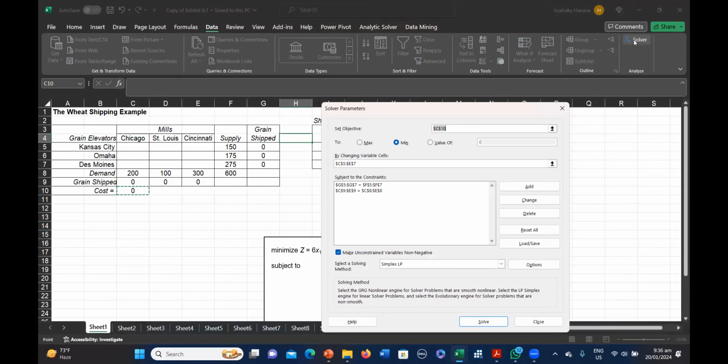So when you click on your solver, you will see this window showing up where the solution has been set up, but you can reset it for us to go through again. I've seen that a number of you don't save your time to go through the motions. You just leave it like that. So if you want, you can reset it so that we go through how to set the objective. This is the function, the cost is the objective cell. So that's what you pick.